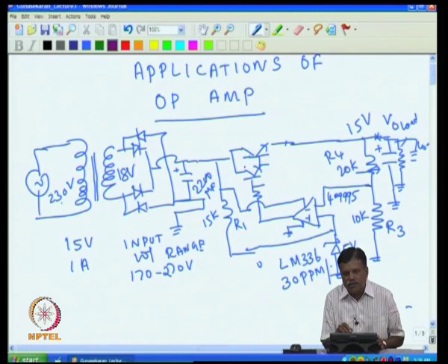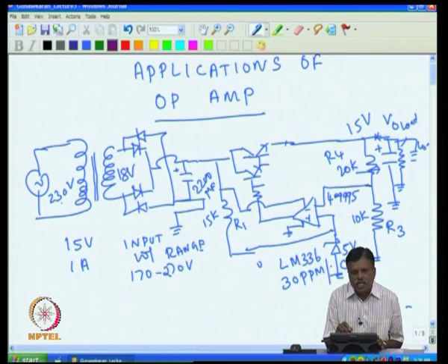So, if you see a TV, typically there will be 3 thermal cycles. The temperature goes up, then comes back, and noon again goes up and comes back, and again in the night goes up and comes back. That means 3 times it is heated and cooled in a day. That means in a year roughly 1000 times it is heated up and cooled.